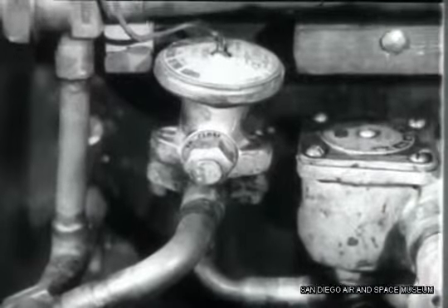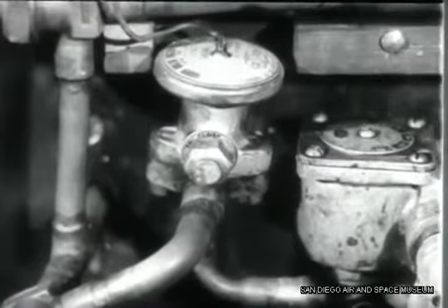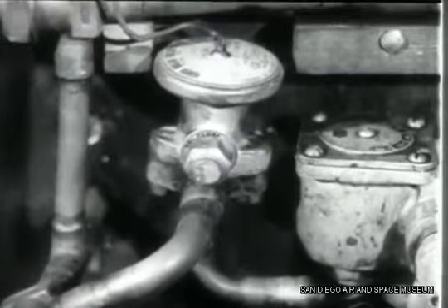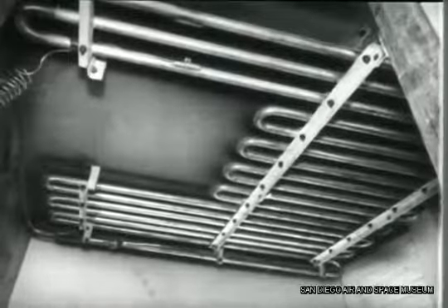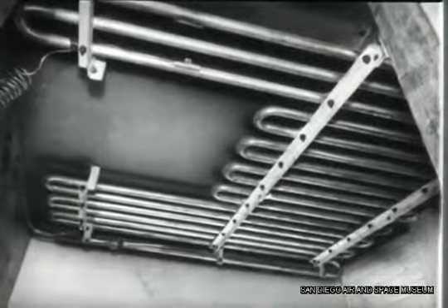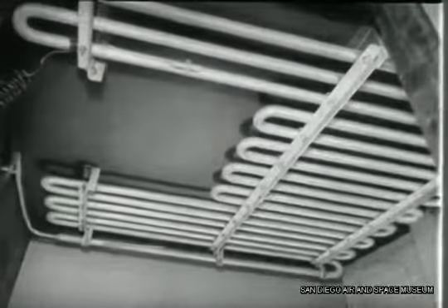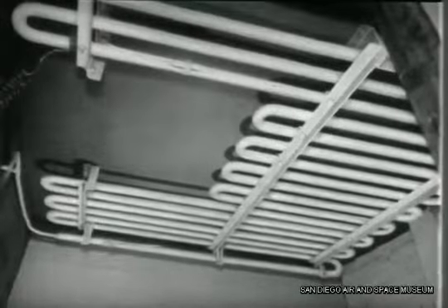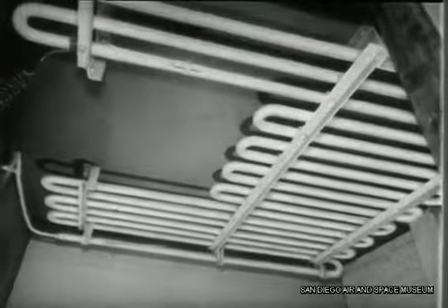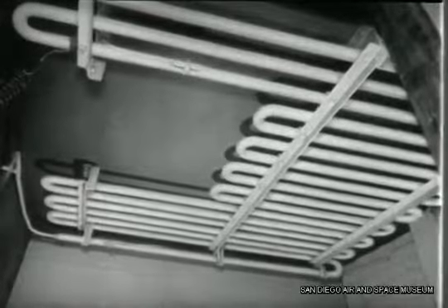This is the thermal expansion valve, where the high-pressure liquid refrigerant breaks up into small particles and expands, coming out as a low-pressure liquid and going into the evaporator. Here, the refrigerant evaporates and absorbs the heat from the air and food in the compartment. If the temperature produced by the evaporator is low enough, any moisture in the air around the evaporator will freeze and form a frosty coating on the coils.